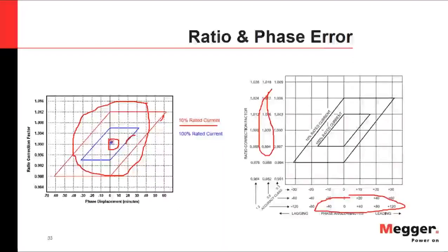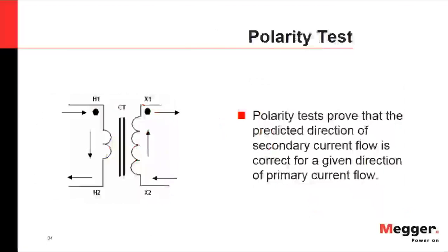For the polarity test, one of the most important things here is not to avoid the test of polarity and make sure that you are clear on what the direction of the current flow is in your circuit. If you are in the field and you're working on a protection scheme, if you have inverse direction of the current, you will create a fault in your system,